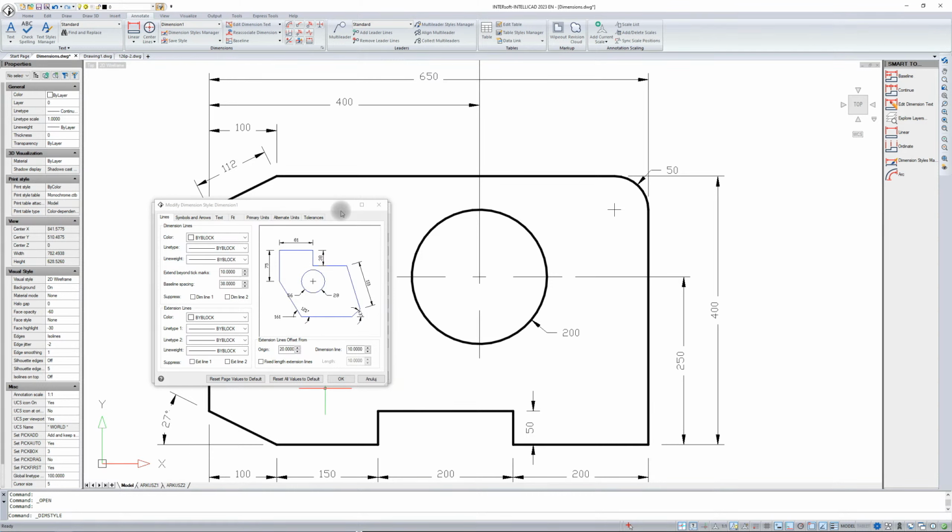On the other hand, if you describe an element by reference to one of the points, as shown here, that is a base dimension. And now for the distance that automatically inserts with the base dimension. That is the distance that is now showing between these lines, and automatically this next base dimension will show above the line that you have already entered.